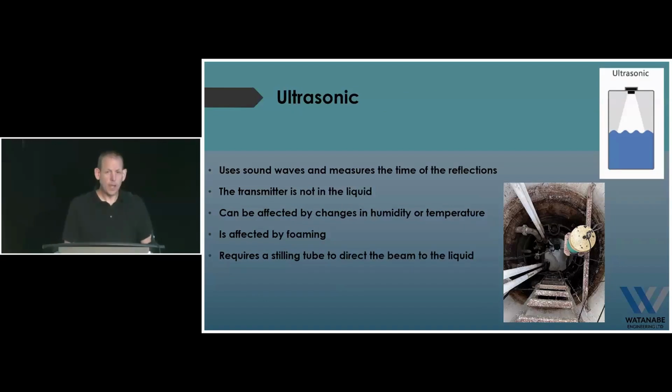So hands up if you've got ultrasonic. Anybody using these? Okay, so Siemens, we see the Siemens product up there quite a bit. This one's a Siemens transmitter that you see on the screen here. So this is one of the technologies that's high and dry out of the liquid. Very good technology, has been around for years. Part of the reason that this wasn't used, or the float switches were used over this technology, was just the cost of it. This originally would be like $4,000 to $5,000 for the transmitter, because you need the actual sensor and the transmitter together. But now, that cost differential's changed a little bit.